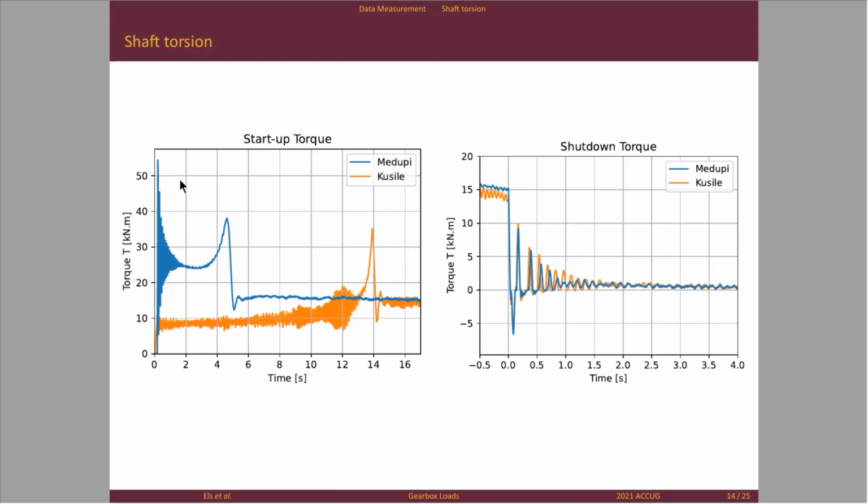It is not the frequency of the fan or the gearbox or anything. As the poles of the induction motor start up, you get those large torque peaks there. It dampens down a little bit, and then just before you go to your final speed, you get that peak.